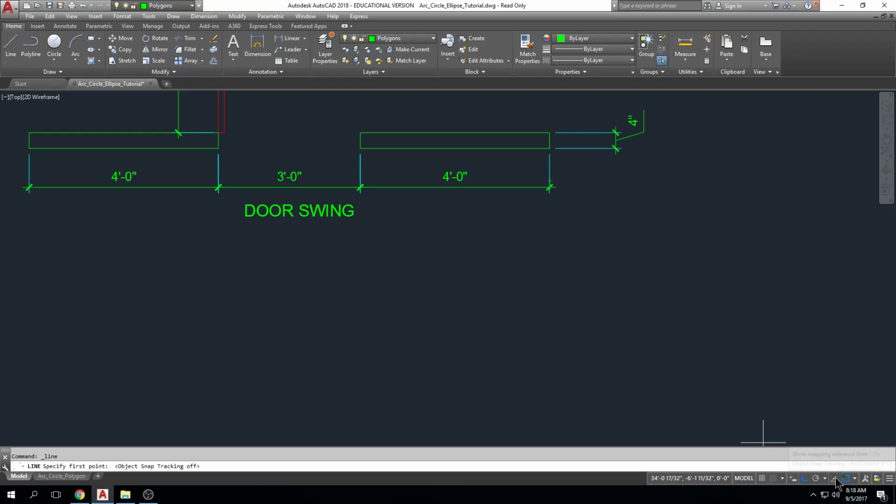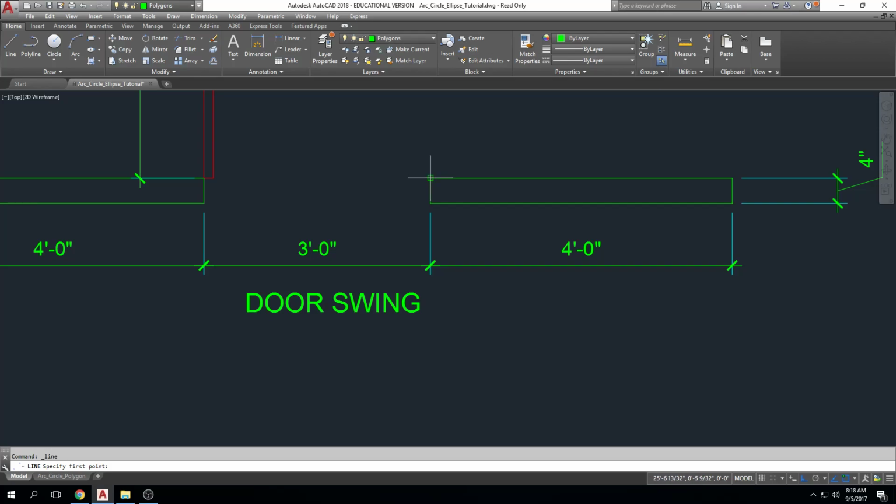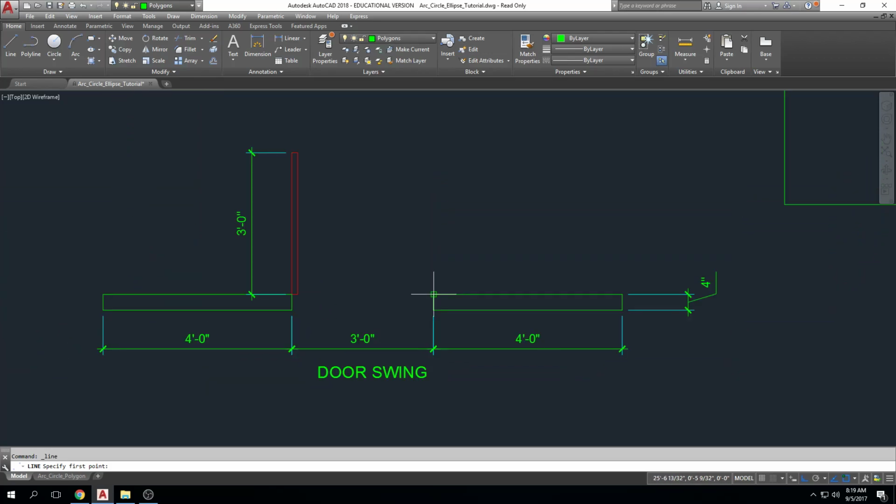There it is. I'm going to turn it on and off just to let it remind itself that it's supposed to be turned on. There we go. It's this little guy right here. I touch something, move in a direction I want to initiate a command, and you see it drags a little line down. That's helpful because, for example, if I'm trying to find the midpoint of something, instead of drawing a bunch of extra geometry, I can hover from the midpoint of that door, come over here, and they snap and line up and I can start drawing. It's a visual drawing tool.